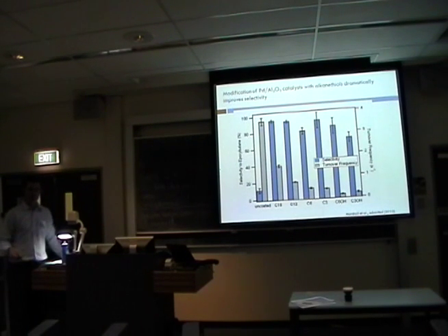When we modify the surface with these alkane thiols, we're able to achieve very high selectivities. This shows a selectivity of about 90%. If we change the operating conditions, we can get to 99% with these kind of organic modified surfaces. And one interesting thing that we see is that the selectivity is pretty high across the board for a variety of self-assembled monolayers on our catalysts.